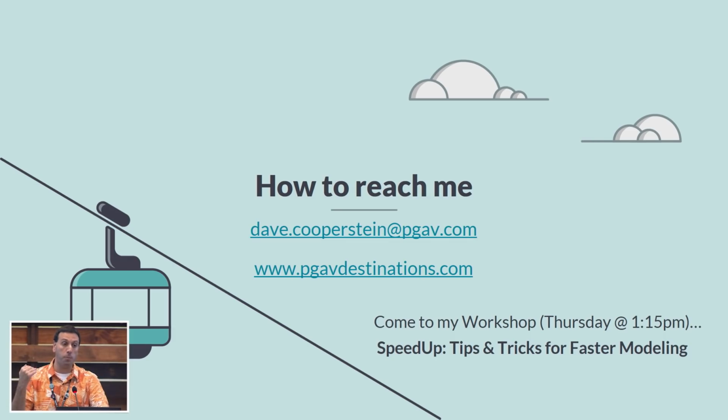And there's an extension called Put on Layer that makes it way easier to move an entire group of things. It digs all the way down into groups and subgroups and puts everything inside of a group on a layer. So I can really control what objects are on what layers. And then I use scenes to manage my layers. If you come to my workshop tomorrow at 1:15, I'll talk about both of those things.